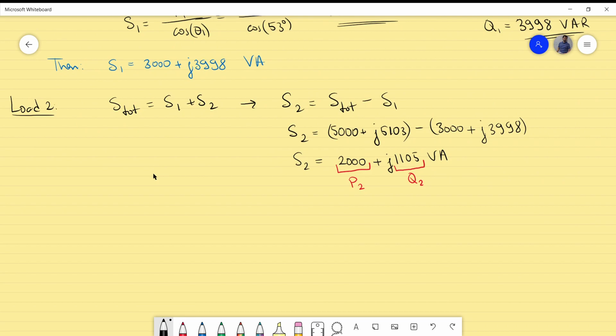We have the imaginary and the real axes. We have the real power for the second load, the imaginary power, which is jQ2, and the apparent power, which is the vectorial sum of both, this arrow S2. And again I have theta, specifically theta 2.